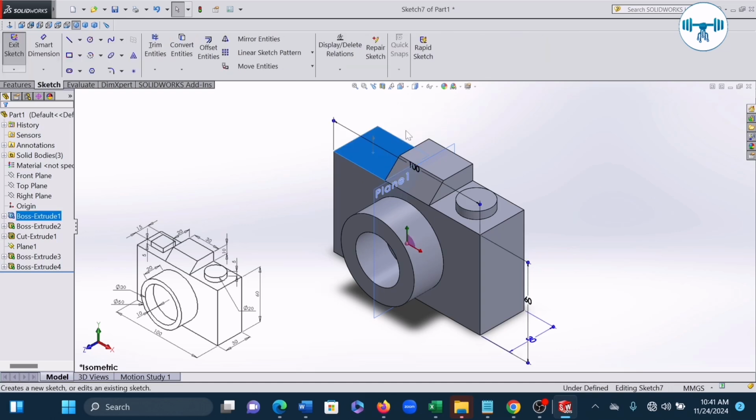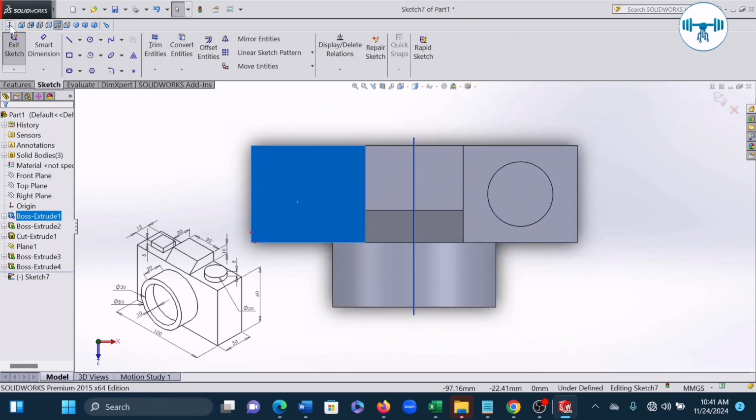So click on it, sketch, put it normal to right. I'm going to put it normal to, and then what do I do next? I'm going to draw the box. Again, the box is positioned at the middle, and the box is 15 by 15, a square. That's why they just gave us one side of it. It's 15 by 15 and then a height of 5.